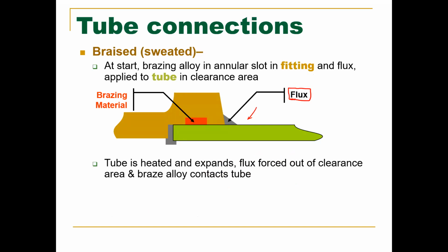So if you're trying to wire up and solder two things, and it's not solid strand wire, all right? It's all those little tiny wires. You dip both those sides in flux and then you twist them together, all right? The way to ensure that the solder material gets deep into all those crevices and makes a really solid electrical connection is the flux, because it will flow. It will move. Once it's heated, it will become that liquid and then it will boil off. But that liquid point is what we're searching for.